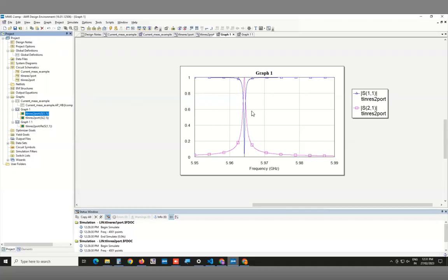Here, I've now shifted both measurements to the two-port system. So blue is the reflection coefficient from one of the ports, and you saw what it is. It goes from +1, no reflection, to perfect absorption. Sorry, all reflection to no reflection, which is perfect absorption here. But absorption here means what? The transmission line still cannot dissipate any energy, right? It can. So, because we have a second port, we looked at there and we see that at that same frequency, the transmission magnitude is 1. So that's where all the energy is going.